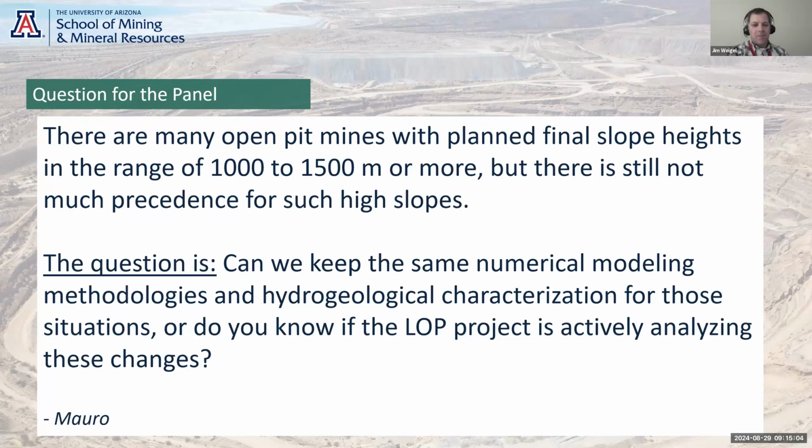I mean, what we do have is the advantage of long data histories. So I would say a lot of what we're relying on is just our data history with our piezometers. We're watching the drain down as the slope progresses. We're watching for things that are not behaving the way we expect them to. I think it's a difference between a brownfield site and a greenfield site in some respects.